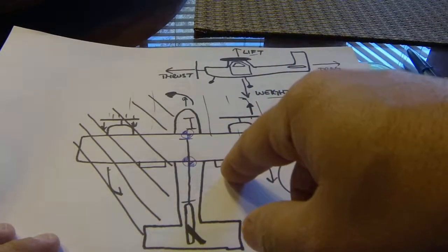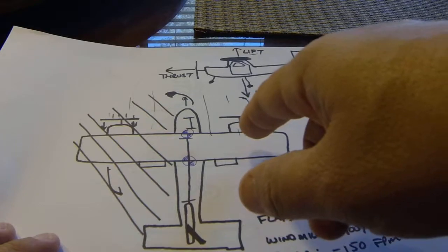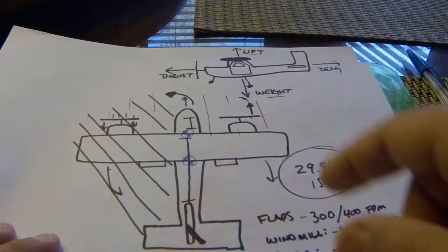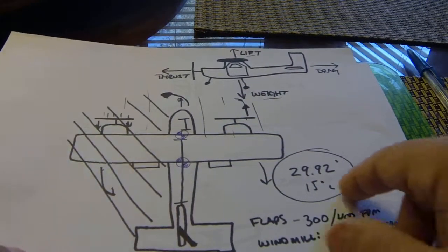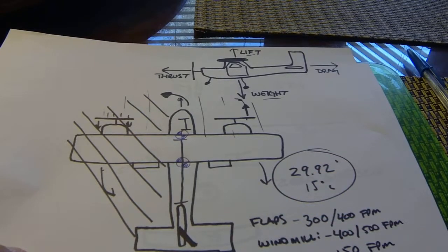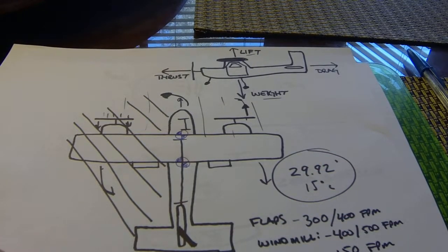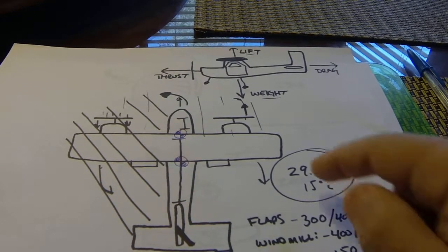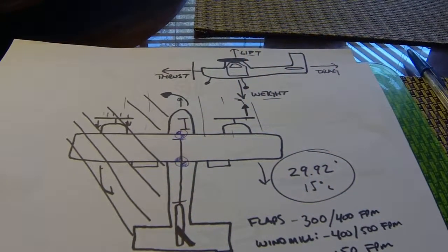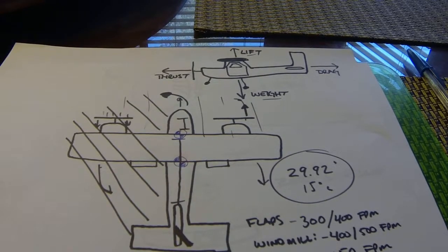If our aircraft is not certified for sustained level flight on one engine, then we need to start immediately thinking about our best glide speeds and cleaning up the airplane and letting this engine do its job as best it can.